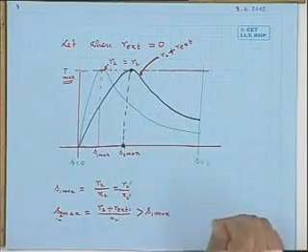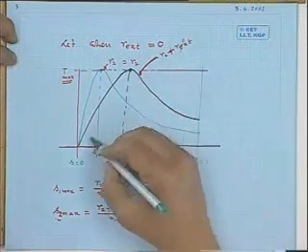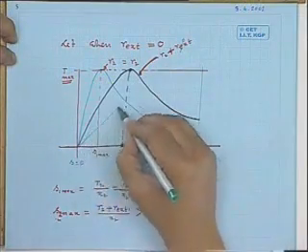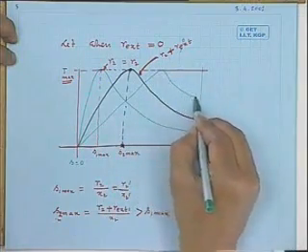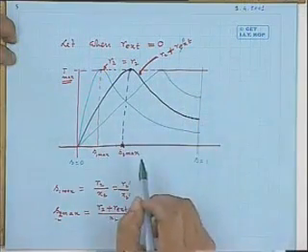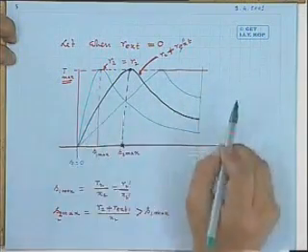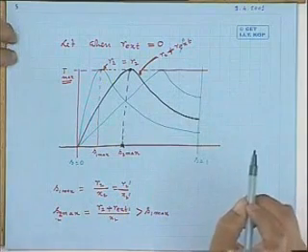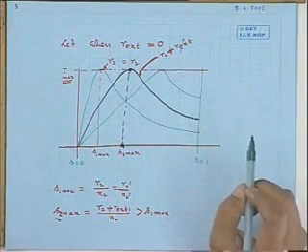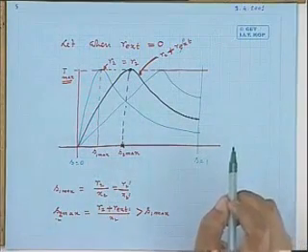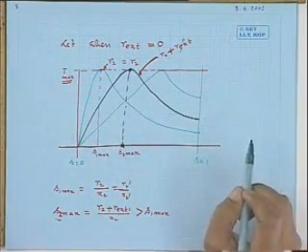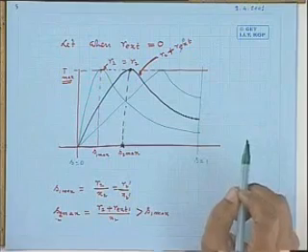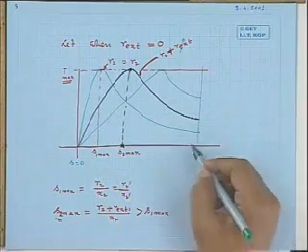In this way, you can imagine that if I go on increasing the rotor resistance, R external as a parameter, these curves will further shift to the right. I can further shift it to the right by simply increasing the value of rotor resistance. Do you think it can help me in any way? What do you observe?